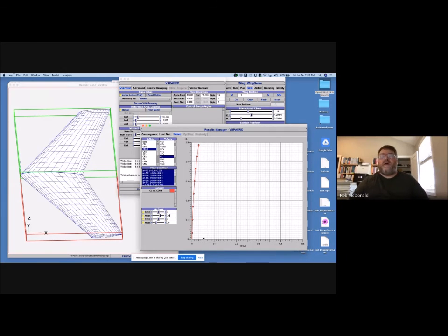So here we are. Here they are in equal axes. If you were to draw a line from here to any point on this curve, the magnitude of that line is the magnitude of the total resultant force, and the angle that line makes with the free stream is the angle of the resultant force. So Gustav Eiffel, with his wind tunnel, plotted the total resultant force in polar coordinates and called it a drag polar, and that's what we still use today.